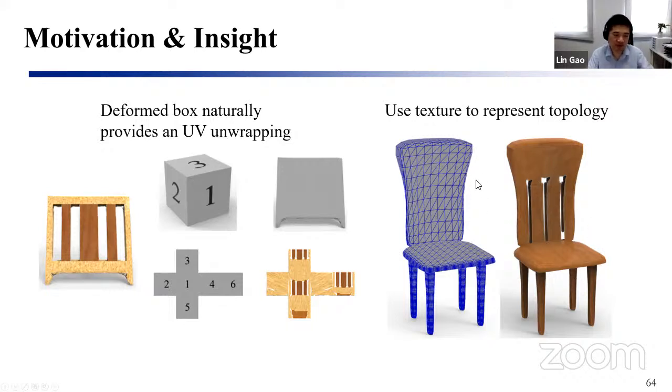We use the alpha channel to define the transparency, and although this part is watertight, with the help of the transparency, we could view some holes. So this is a trick to represent complex holes or complex topology. This does not actually solve it, but with some tricks we could generate some models with complex topology.